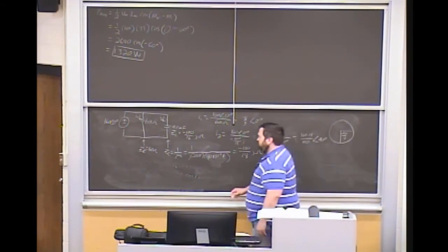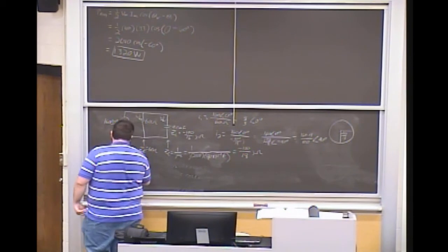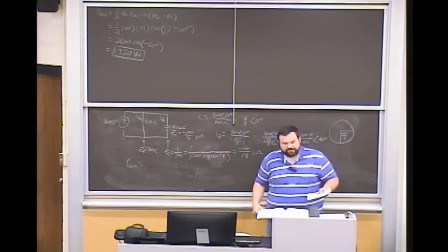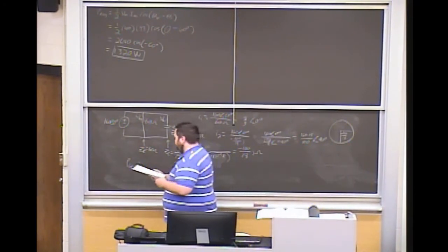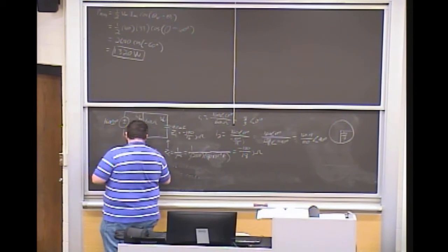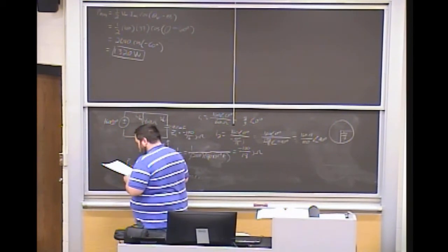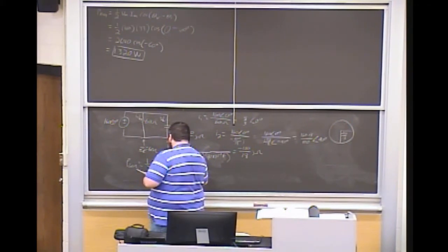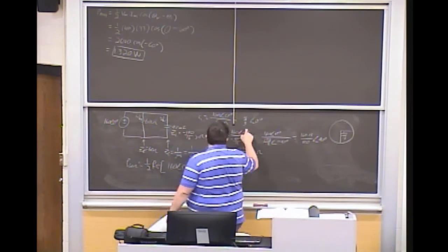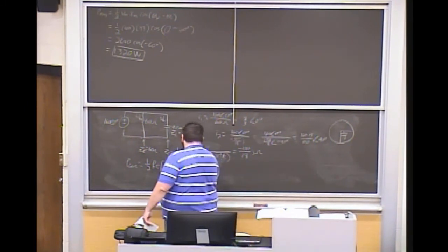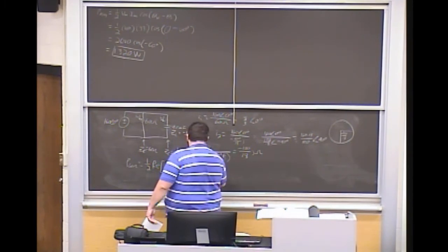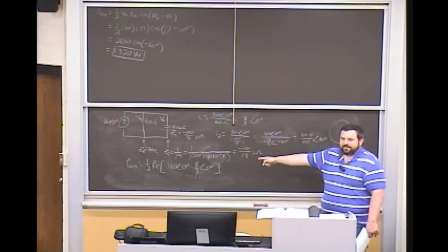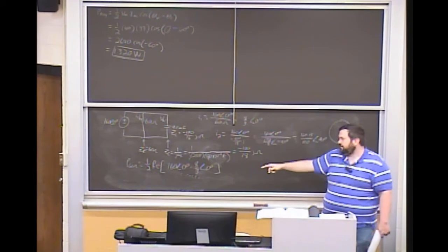And so, let's go about figuring out our average power. So the power at the 60 ohm resistor is going to be, now this is where we're going to go back to the phasor and the real part. 1/2 of the real part of our voltage phasor. It's going to be 160, 0 degrees, times our current phasor, 8/3, 0 degrees. As it turns out, that's all real, right? Because we have 0 degrees.